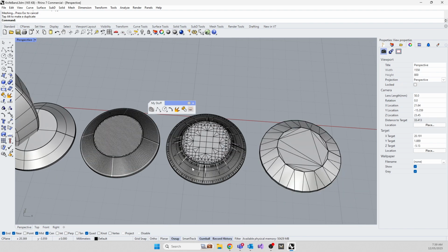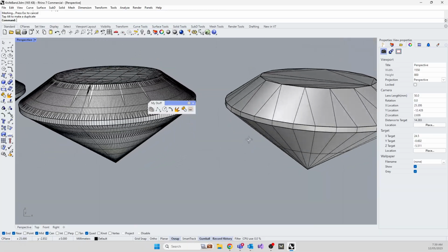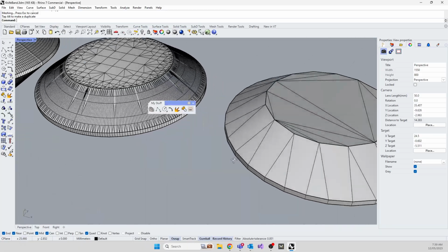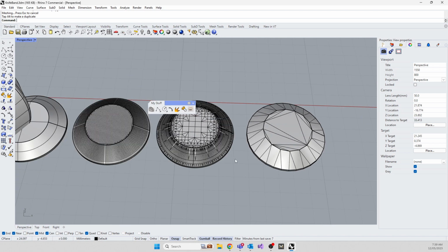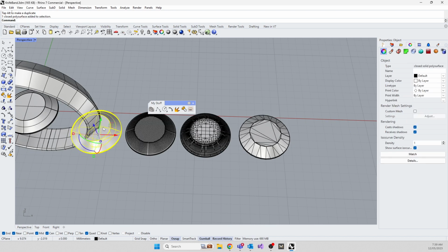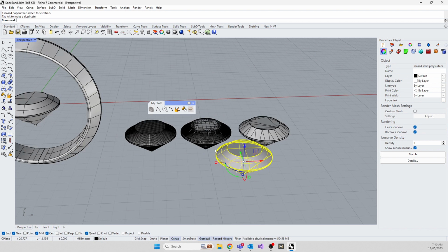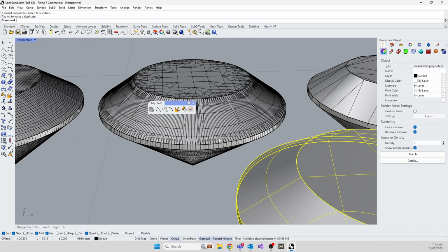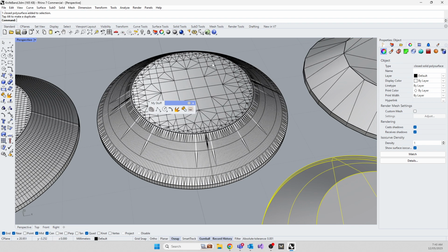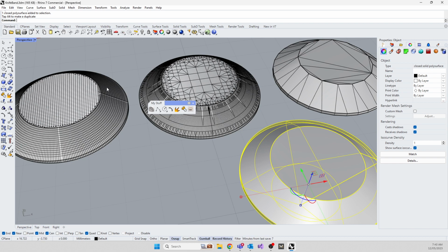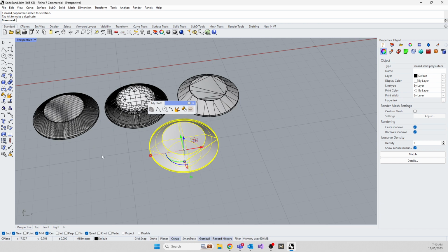So you notice something about the one with very low polygons? It kind of looks diamondy. You with me? Or you can control how many polygons you want, and you can get really down and dirty on it. So Rhino's default meshing is rubbish. In my opinion, it's garbage. I wouldn't use that mesh. It's all over the show. It's messy. I would prefer to control my mesh, which is the first window that you saw.